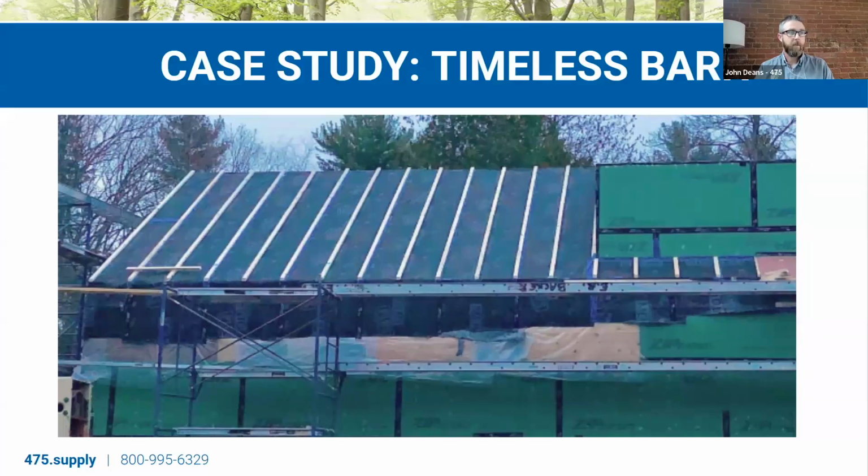So underneath all that, the IntelliX has a little flap that's coming down that we can't see here. The Mento Plus is coming down as well, so we can sort of encapsulate the insulation airtight on both sides. And we're totally weather tight at this point, right? One of the reasons we were doing this in sections is we had a lot of rain during this assembly, so we were on and off and had to tarp sections. But it meant that as we built this, we could be weather tight throughout the whole process.